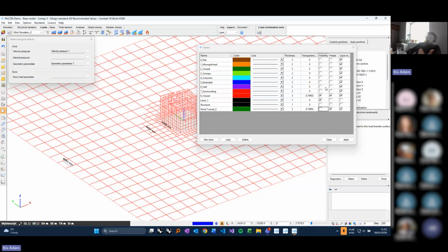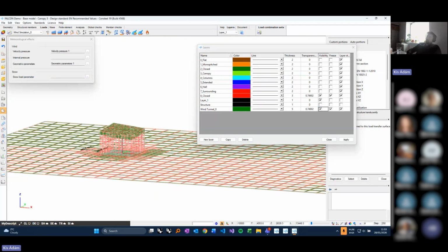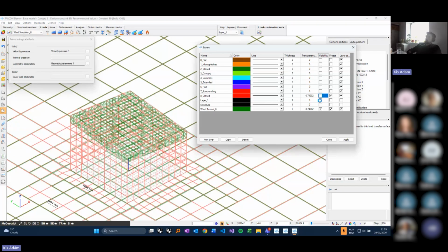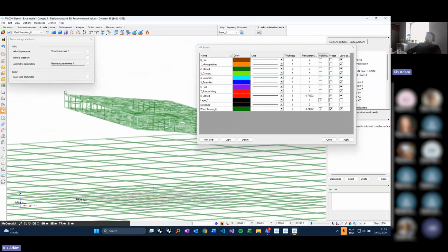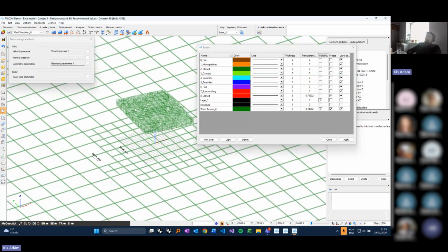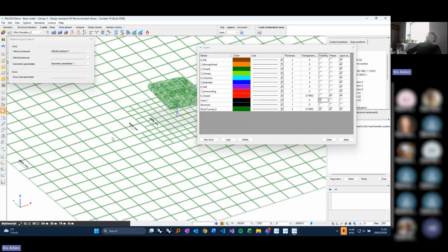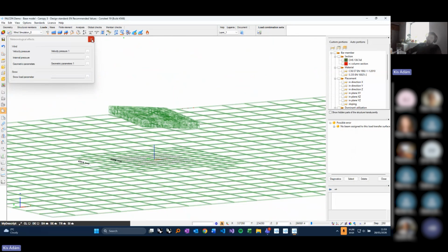Okay, so this was our previous setup, and let's see the setup with only the canopy. As you can see, it is pretty similar, but because of the 1 meter mesh size, we have 2 mesh faces on the canopy, and pretty much the rest is similar, because from 1 meter we had a refinement factor of 3 and we end up with the same result.